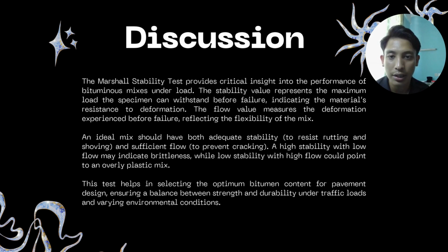Lastly, discussion. The Marshall stability test provides critical insight into the performance of bitumen mix under load. The stability value represents the maximum load the specimen can withstand before failure, indicating the material's resistance to deformation.